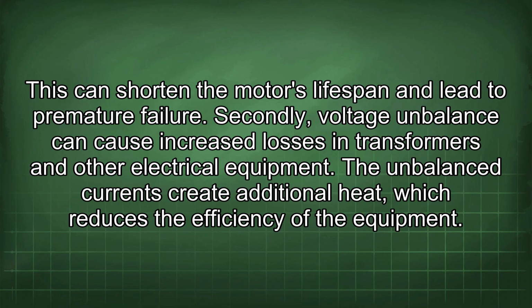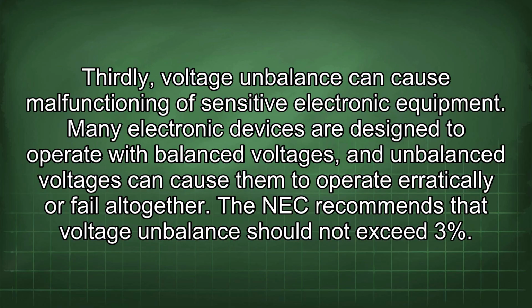Secondly, voltage imbalance can cause increased losses in transformers and other electrical equipment. The unbalanced currents create additional heat, which reduces the efficiency of the equipment. Thirdly, voltage imbalance can cause malfunctioning of sensitive electronic equipment. Many electronic devices are designed to operate with balanced voltages, and imbalanced voltages can cause them to operate erratically or fail altogether. The NEC recommends that voltage imbalance should not exceed 3%.